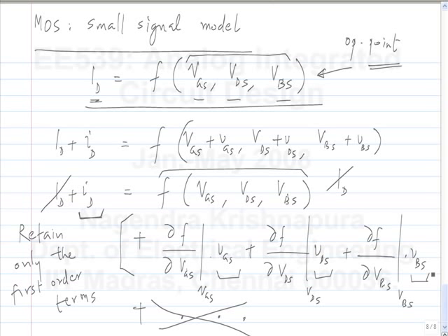So, you have a certain set of voltages applied to the MOSFET, you get a certain current. Let us imagine a small change in the applied voltages, you get a different current, which can of course be calculated from the nonlinear function. If you know the nonlinear function, you can calculate it. But let us say what happens when we expand the nonlinearity as a power series.